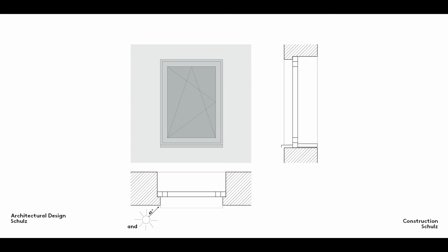Assuming that the sun hits the exterior wall at a lateral angle of 45 degrees in the plan view, draw guidelines at this angle from the shadow casting edges to the edges of the faces onto which the shadow is cast. Repeat the process with the section view, assuming that the sun hits the facade at an angle of 45 degrees from above.